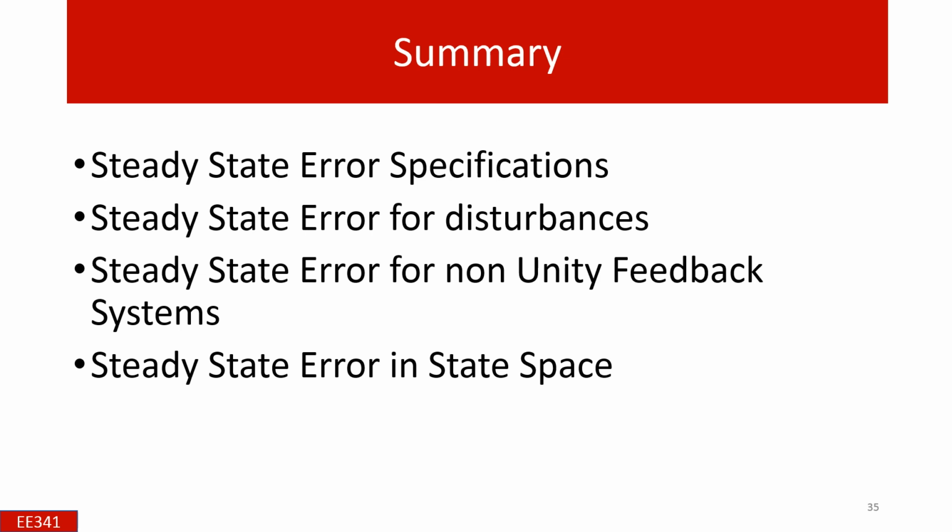Just use the closed loop transfer function, which is already derived many times in the course, from the given state space information, substitute into the normal relation to find the error signal, and from the error signal find the steady state error.